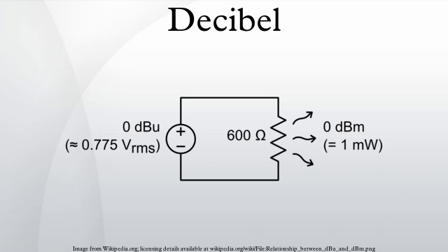The decibel may be defined by the statement that two amounts of power differ by 1 decibel when they are in the ratio of 10^0.1, and any two amounts of power differ by n decibels when they are in the ratio of 10^(n×0.1). The number of transmission units expressing the ratio of any two powers is therefore 10 times the common logarithm of that ratio. This method of designating the gain or loss of power in telephone circuits permits direct addition or subtraction of the units expressing the efficiency of different parts of the circuit.